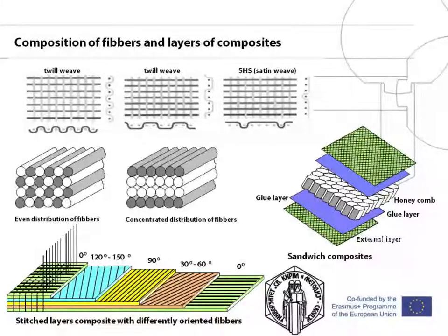Reinforcing fibers contribute to the mechanical strength characteristic of the composite. The strength is dependent on the type, amount, orientation, fiber surface treatment, and the compatibility of the fiber with the matrix polymer. By varying these parameters, a broad range of mechanical properties are possible.